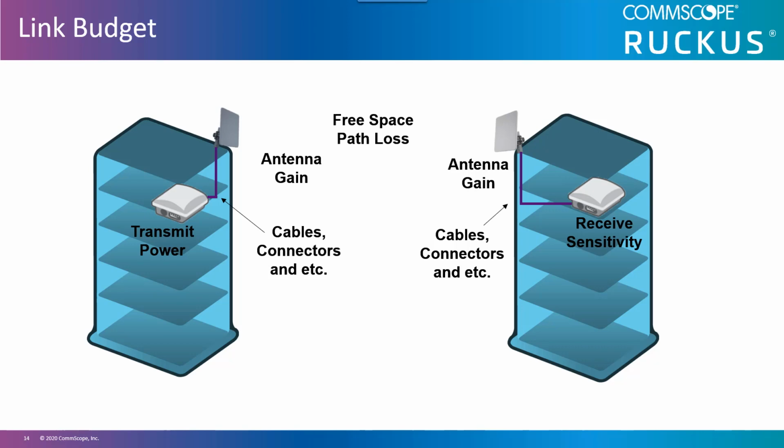Link budget. The link budget is an important step in wireless bridge design or outdoor meshing. You need to make sure that you stay within the legal transmit power and that your link performs as expected even when conditions may change. To do this, you account for all RF gains and losses throughout the entire link with a minimum RSSI goal defined. This goal of signal strength is the absolute minimum objective for the link to function as required.